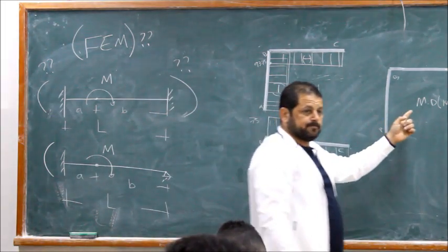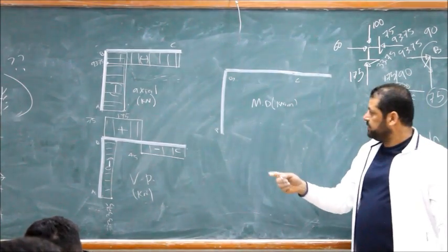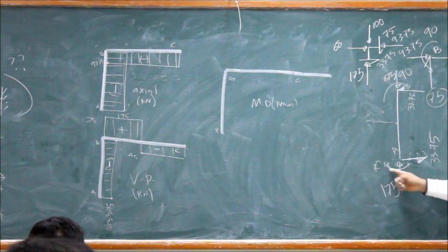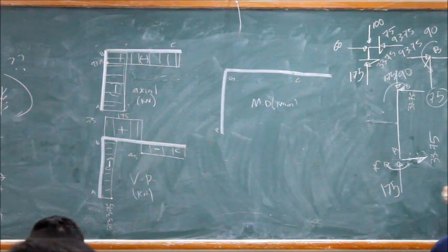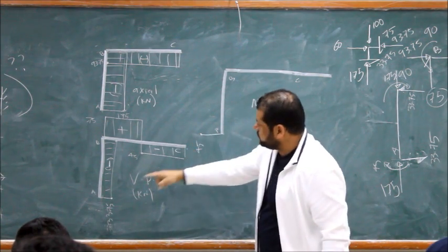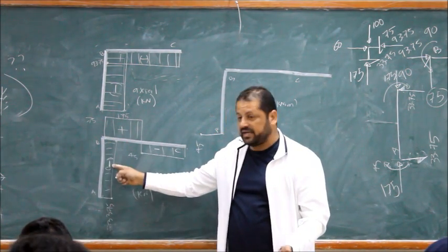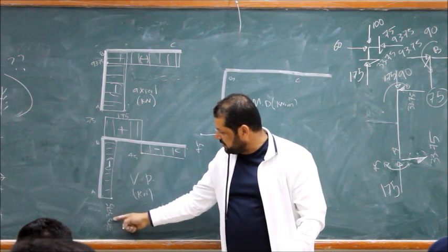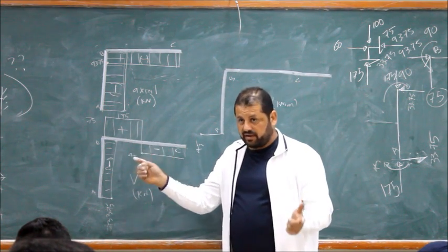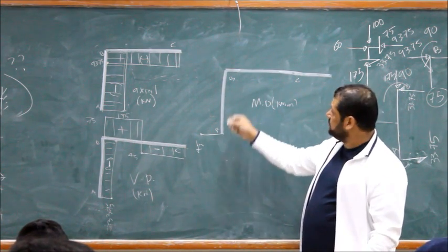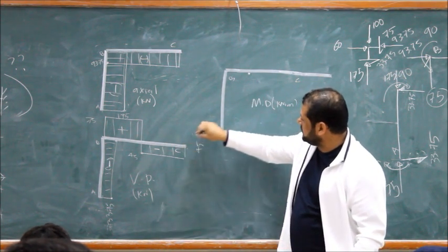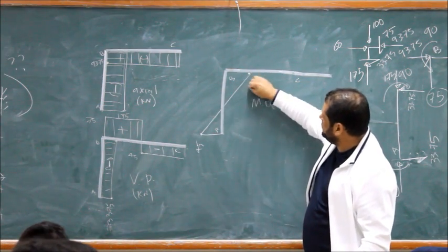You finish? Yeah. Okay, so how much is the moment at A? Positive? Positive. Okay. Positive. So we go 45. As we go from here to here, there is a change, negative shear. The area under this, 33.75 times 4, which is 135, minus 45. We go to 9. This is constant, this is linear. 9.